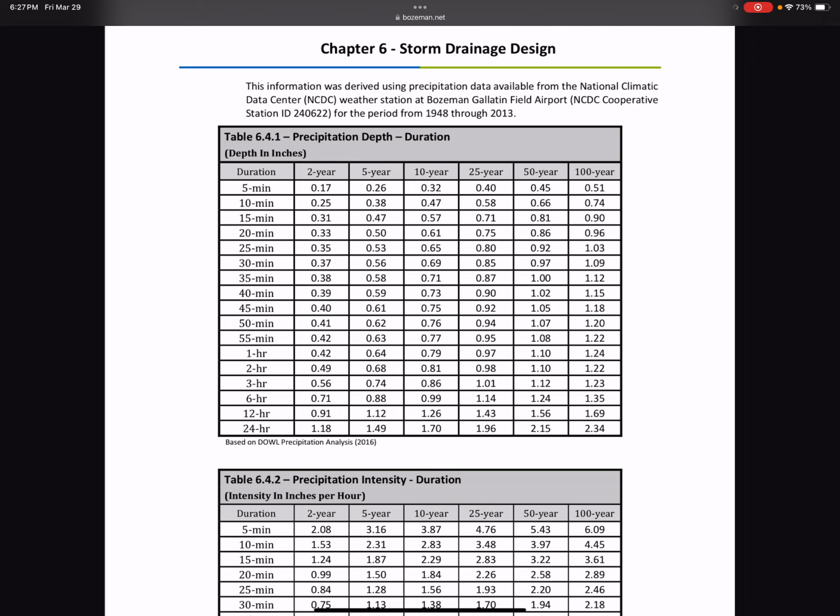So I mean, it's definitely going on the outer edges of what we typically deal with as a structural engineer. But I was just trying to show you the relative magnitudes here. There's 1 inch of water is our storm intensity that we design for. But for snow loads in Montana, we're already putting 6 inches of water on our roof. And so we typically cover this ponding instability. I have done it a couple times on larger structures.